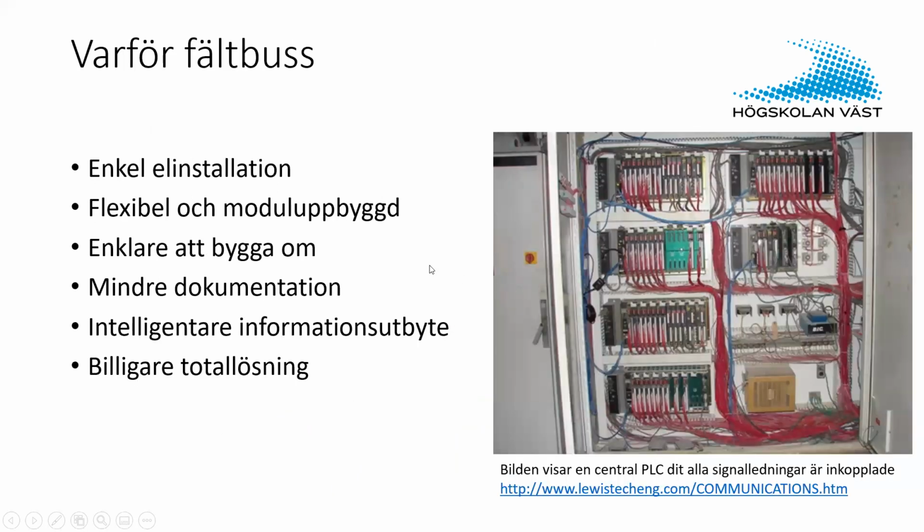Why do you need special field buses then? Well, it's not really about the computer or programming or networking technique. It's more practical reasons. They make it simple to install electrically. It's flexible modules, simpler to redesign and rebuild, with less documentation. It's standardized in some way. Information exchange works in an intelligent way.